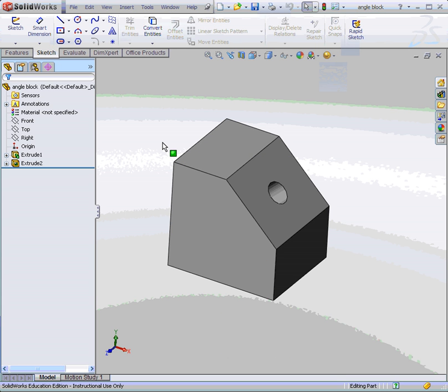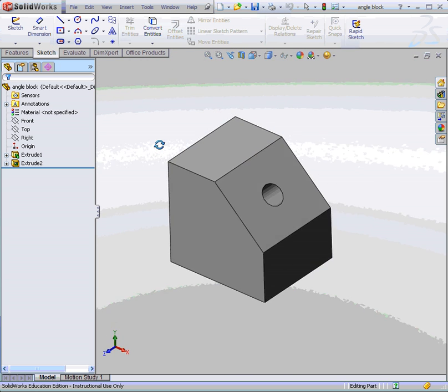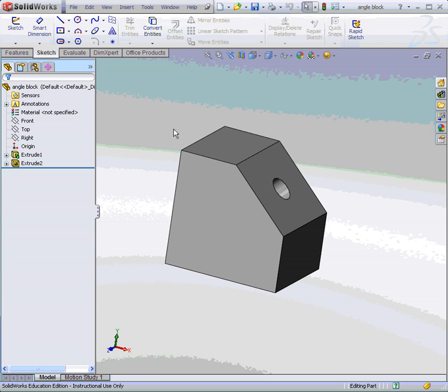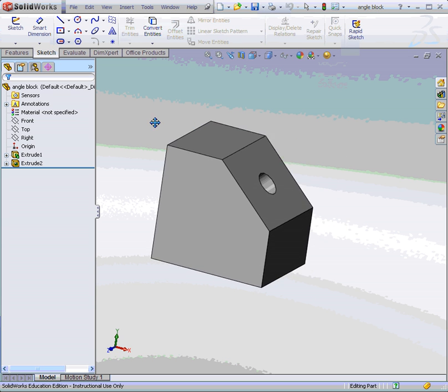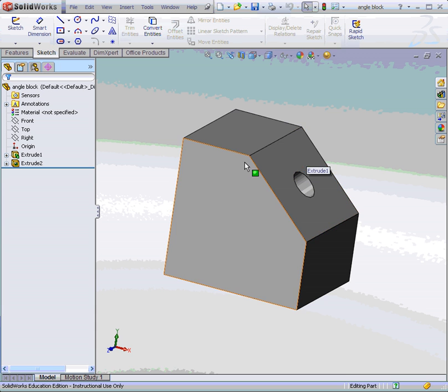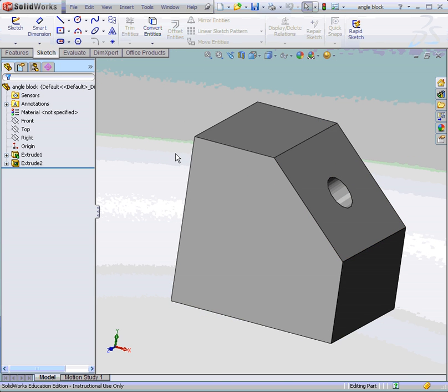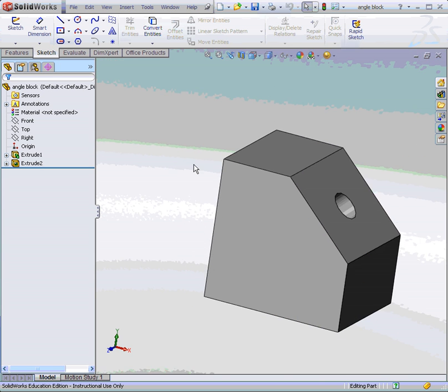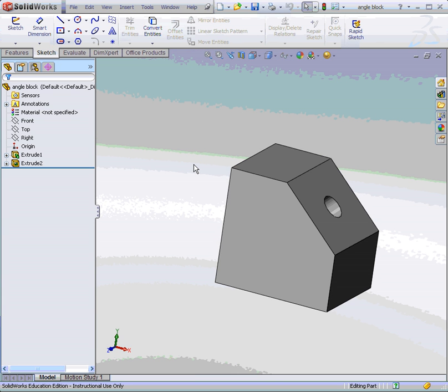The center button of your mouse, which also has the scrolling wheel, is used for model rotation, just by pressing and moving the mouse. If you hold the control key on your keyboard and move the mouse, it pans and shifts the object in your space. And the center scroll wheel, as you roll it towards you, objects come towards you. As you roll away, the object goes farther from you.